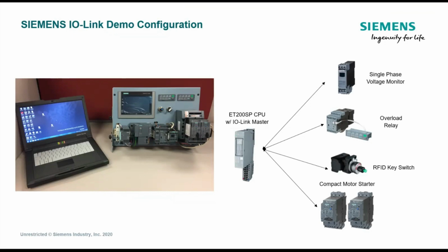So if you ever did starters like this, and you did a comb bus bar up on the top of those starters, and all of a sudden the middle starter failed, it would take you quite a while to undo all that wiring and get that starter replaced. With this compact starter design in this plug-in type of unit, you can replace failed units very, very quickly.